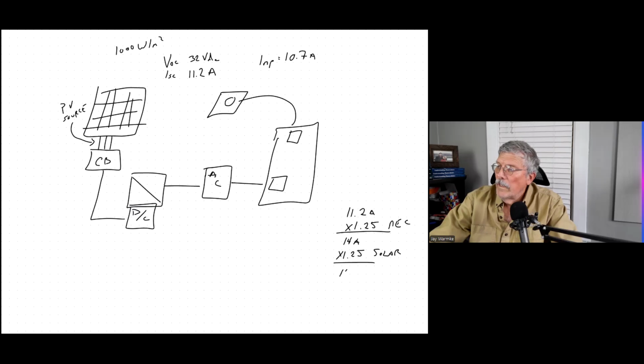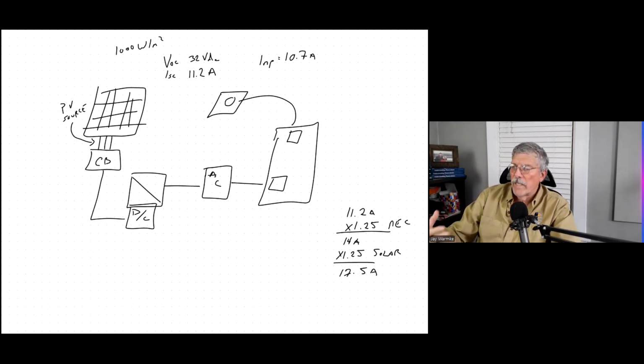So what usually begs the question is, when do we apply that solar variable? We apply it until you hit the first piece of electronics, the first piece of electronics that controls the output of that solar panel. So that might be the charge controller in a standalone system, because as soon as it gets into the charge controller, now it's going to control its output. But it might be a microinverter.